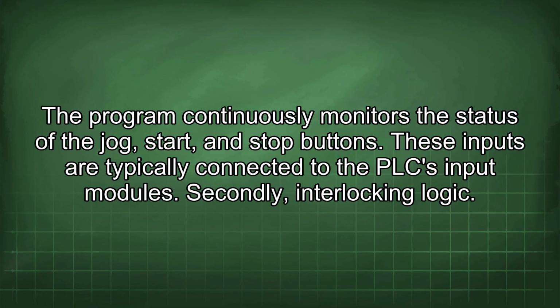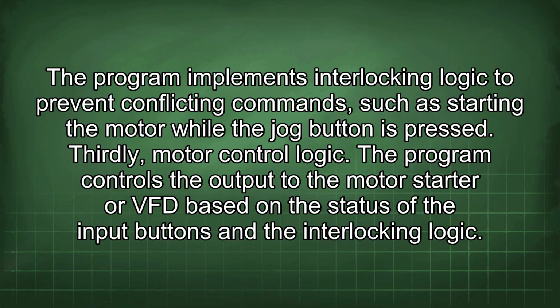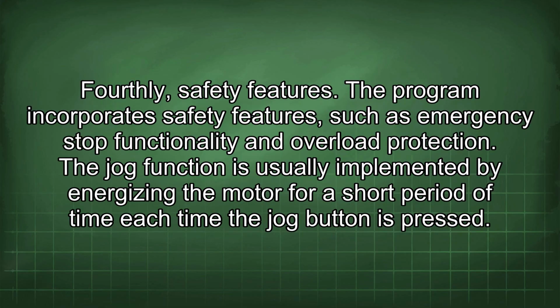Secondly, interlocking logic. The program implements interlocking logic to prevent conflicting commands, such as starting the motor while the jog button is pressed. Thirdly, motor control logic. The program controls the output to the motor starter or VFD based on the status of the input buttons and the interlocking logic. Fourthly, safety features.